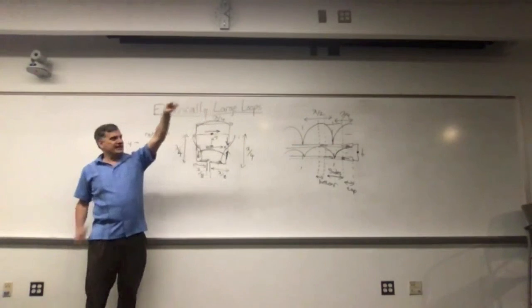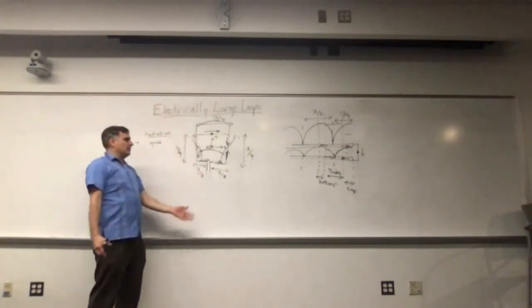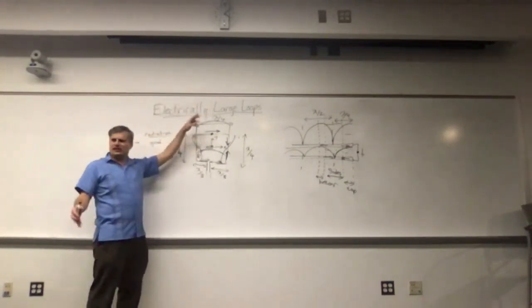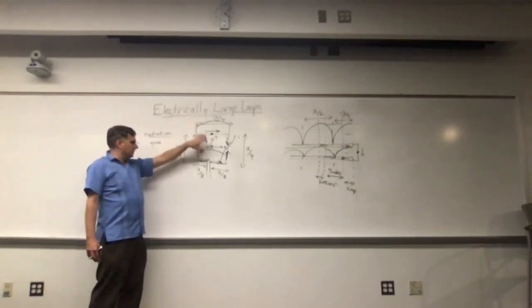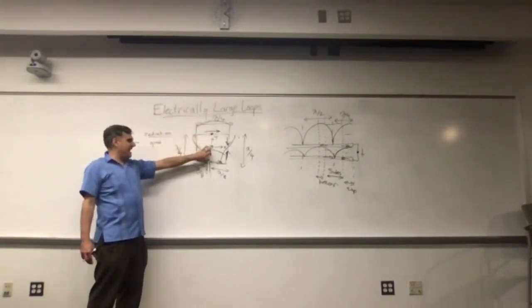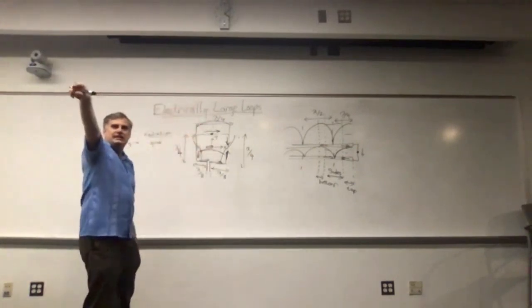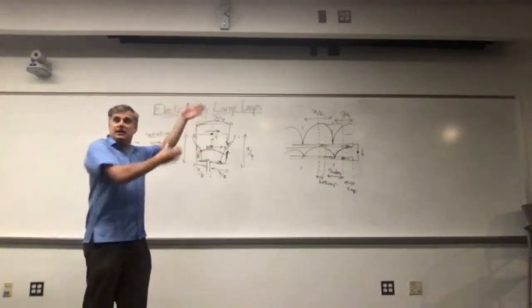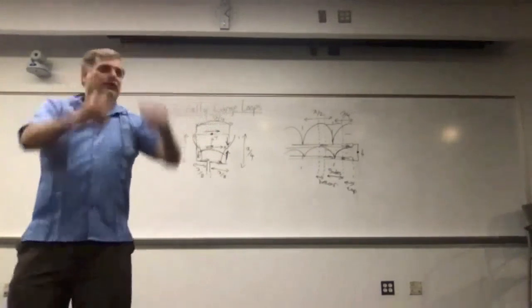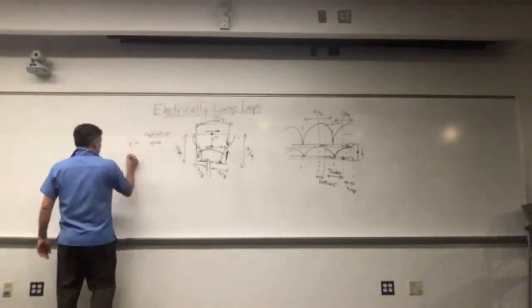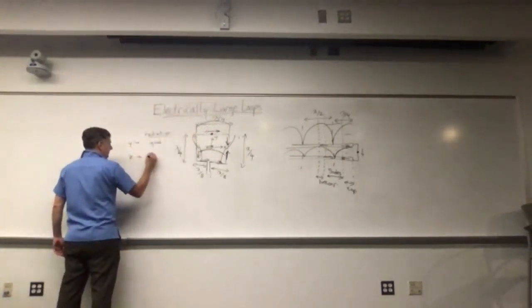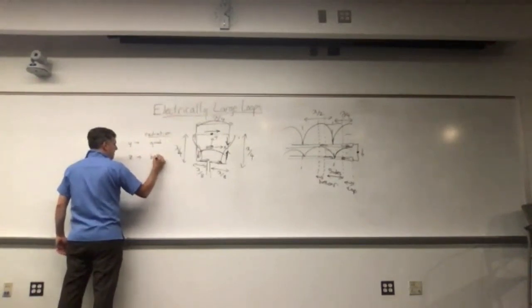So they're radiating omnidirectionally with a big current mass. Probably looks almost like an ideal dipole. And then you have an exact one down here that's in phase. So in this direction, positive Z as well as negative Z, they're going to constructively interfere. I'm going to put Z better.